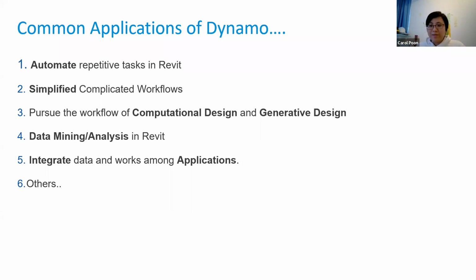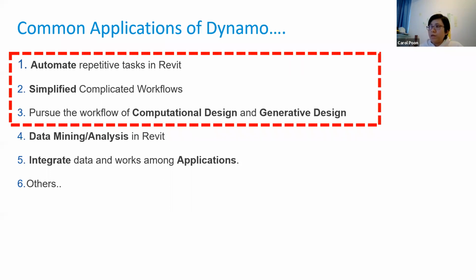But you cannot edit that geometry, so this is meaningless to you. But right now with Dynamo, you can export the coordinates of this bridge in Excel format, and then input this Excel into Revit by Dynamo. It will help you regenerate the bridge model inside Revit, so you can do some opening or editing work in Revit. And we are going to explore these 3 points in today's webinar.